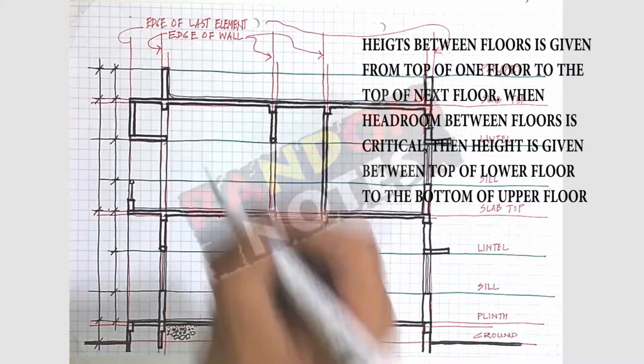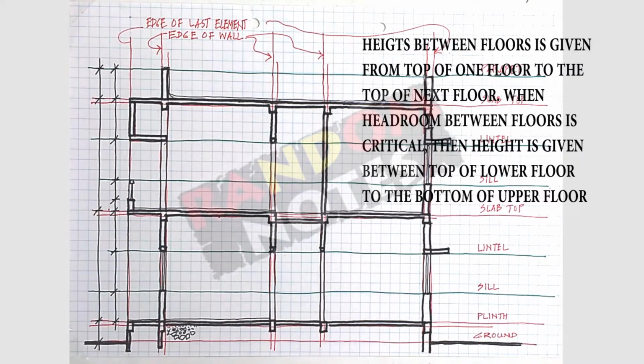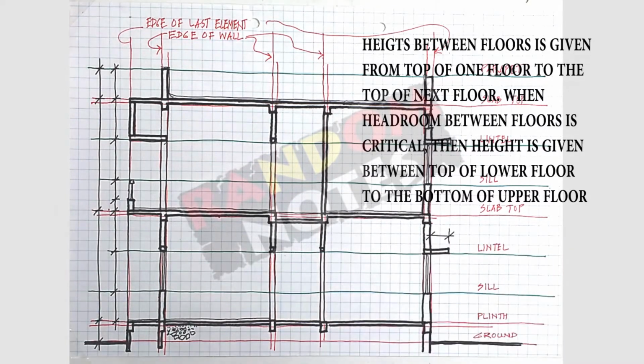Plans are for horizontal dimensions and sections are for vertical dimensions. But there are certain horizontal dimensions which cannot be depicted in plans. So here the width of the chhajja has to be shown in section.